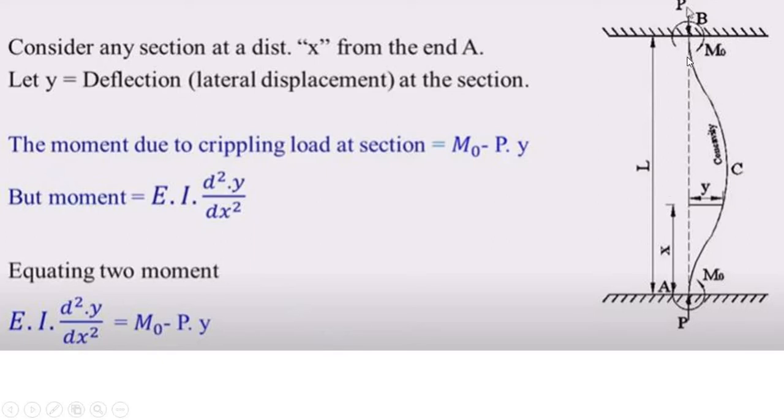So this is the line of action of the force P, and this much is the perpendicular distance, and this force will make an anti-clockwise moment. That is why we put a negative sign.